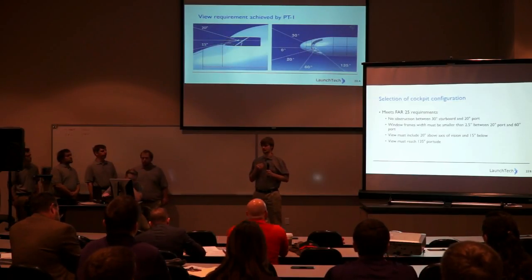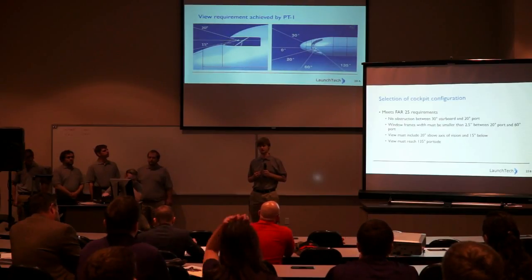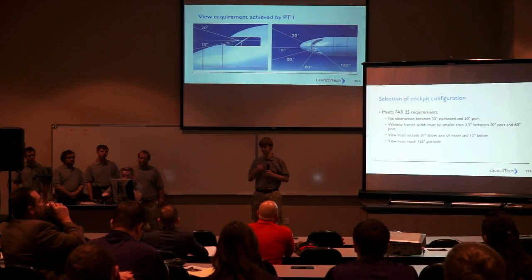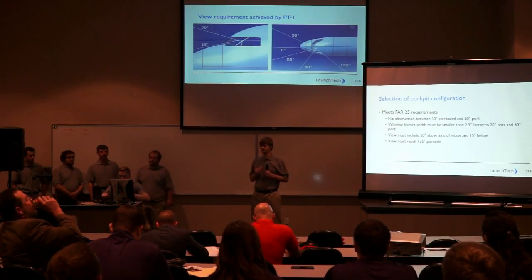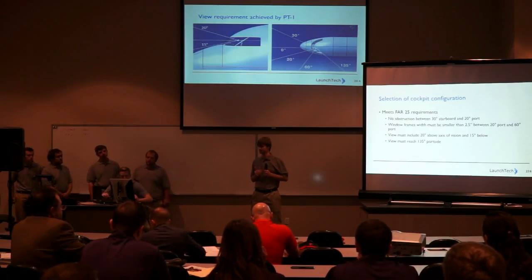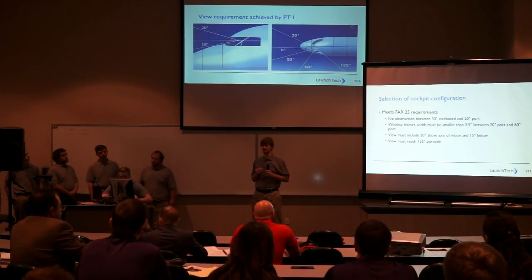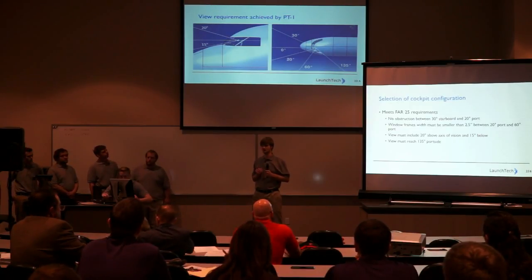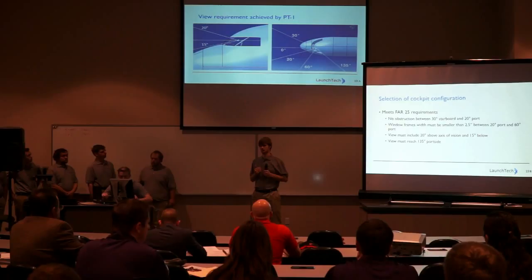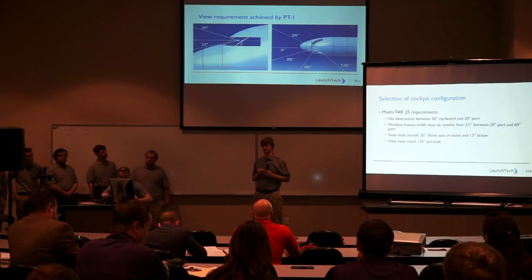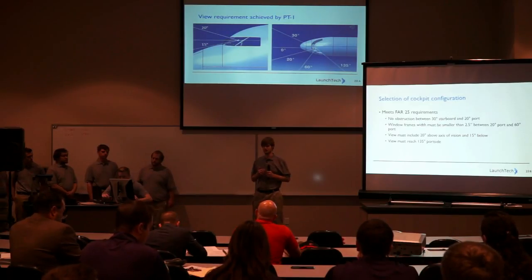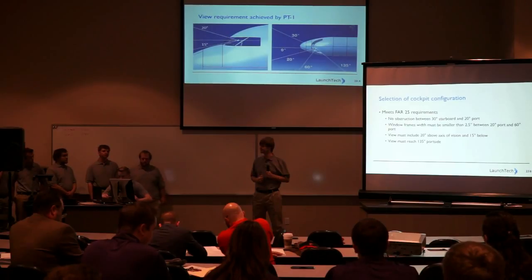The PT-1 was required to fulfill field of view requirements as designated by the FAR 25. The field of view needs to reach 15 degrees above eye level and 15 degrees below. Additionally, there cannot be any obstruction between 30 degrees and 20 degrees from the main pilot. Also, for any obstruction between 20 and 60 degrees, the obstruction can't be wider than 2.5 inches. And the full field of view needs to reach all the way to 135 degrees. PT-1 satisfies all of these requirements.